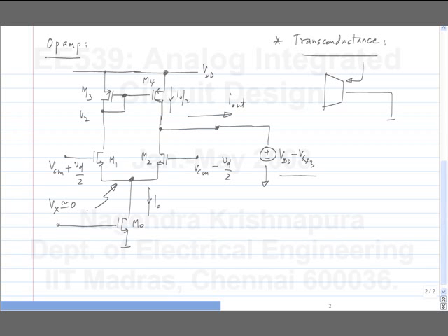But if I try to open circuit the output, if I leave it open, if I don't terminate it with a voltage source, this point will be very far from 0. It can be very far from 0. Also, we can assume that node voltage could be something Vx and then calculate the current that is flowing at out. First of all, that is very much true. You can put the entire incremental circuit and analyze the whole thing. You will get the right answer. In fact, you can do it as an exercise.